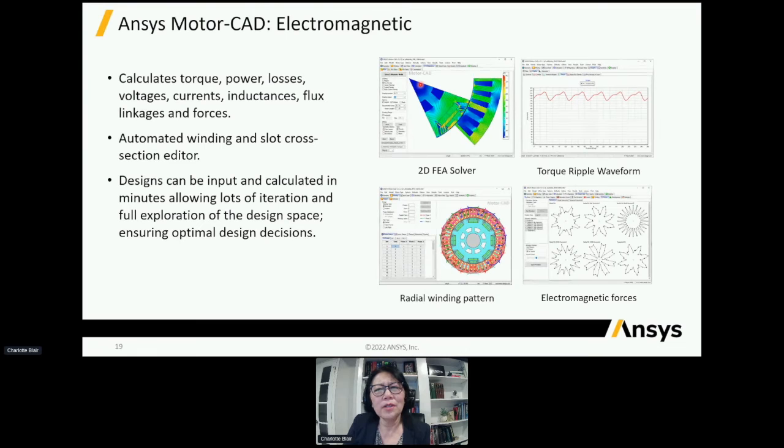So here in this trace, the colored part is really showing you where the currents are, red being hot and blue being cold. You can see that in this scenario, there is interaction when the rotor and the stator are in close contact with each other, that there is coupling of the fields here. They're not all blue, or they're not all yellow. And we want to know where the fields are. We can't see current moving, but in simulation, we can see where they are and what is coupling to what. The most important thing is, what is coupling to what?